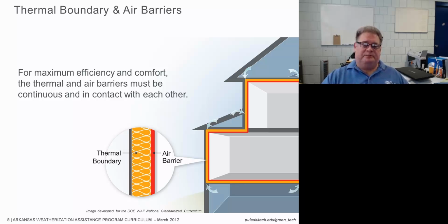If it is not, then you're going to get heat transfer by convection into the insulation. Convection is movement of a fluid or a liquid. In this case, we're talking about the movement of air through that insulation, and it's going to start moving that heat. Instead of having 3.5 inches of insulation or 9 inches of insulation, you're going to have air moving through it.